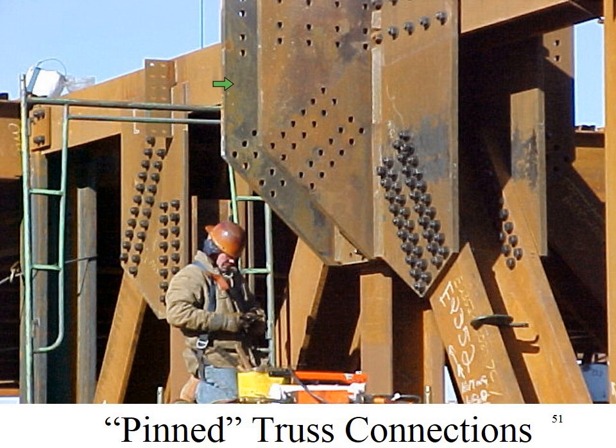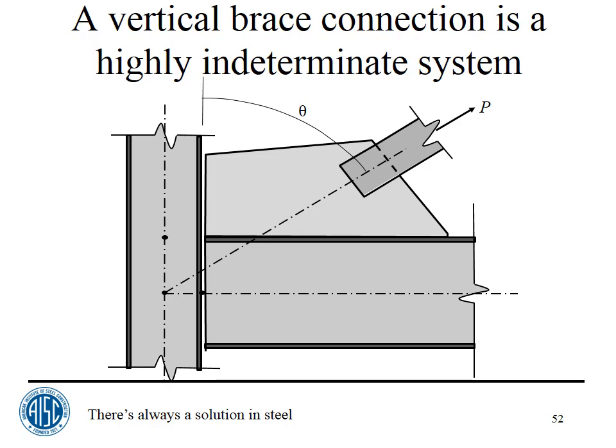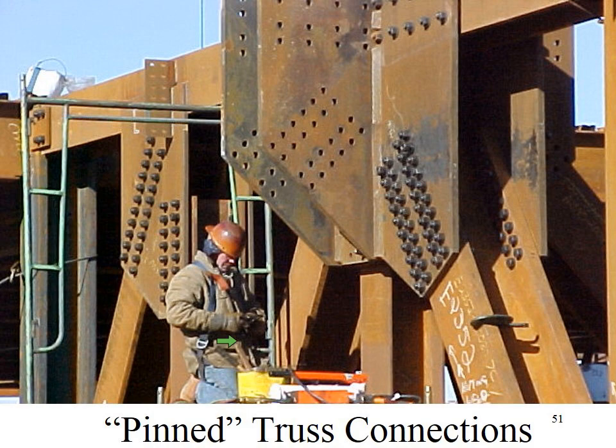Well, that's the way all of this steel was designed, as though all of these members that you see in here, the top chord of the truss, the diagonals, the truss verticals, were loaded with axial forces, tension and compression only. The vertical bracing connections that you saw a moment ago, this truss connection was designed by the uniform force method. I mean, it's not. The uniform force method was developed originally for bracing connections, but really, a bracing connection is just part of a vertical truss. And this is a horizontal truss. These connections were all done in exactly the same way that you would do, say, a vertical bracing connection.